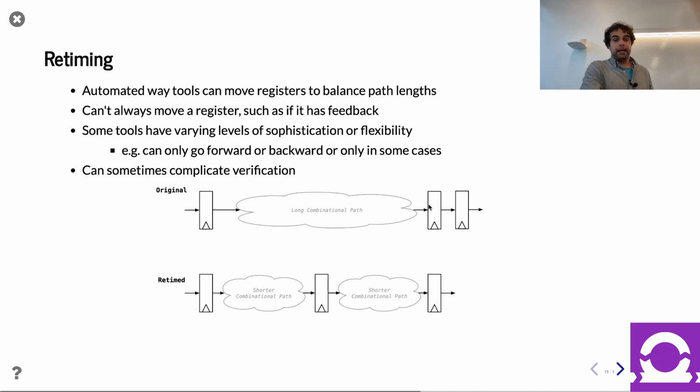It can be done. And so, as a design methodology, for example, in Chisel, we would love to just chuck down some registers at the end and let the tools retime through the design. This works quite well with a lot of commercial grade ASIC CAD tools. Unfortunately, some of the tools, and I'm going to name names, Xilinx Vivado, do not do a great job with this, so you use a different methodology. But in the ideal dream case, that's the way it should work.